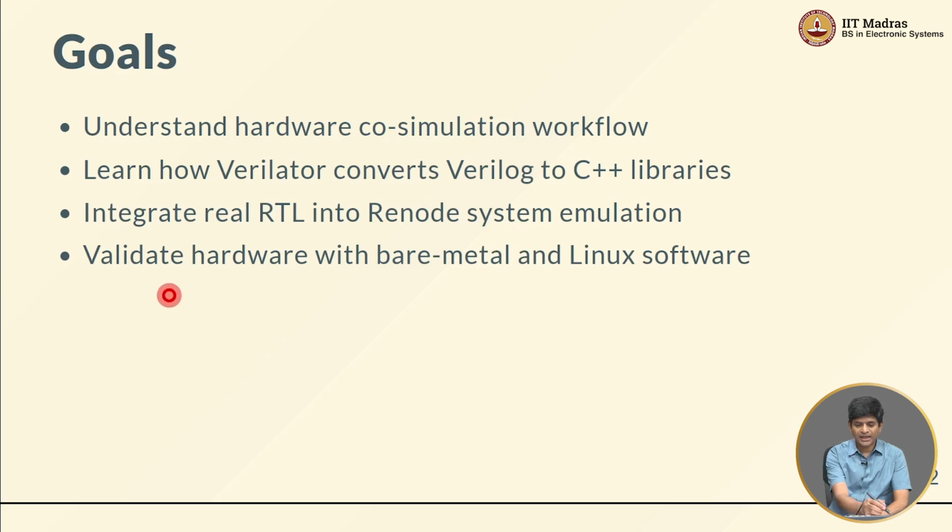And eventually what we want to do is to get this running on real hardware. But right now we are going to focus on validating the hardware with two types of software interfaces. One is the bare metal interface and the other is the Linux based driver and the platform driver based interface. So let's go a little bit deeper into all of these steps.